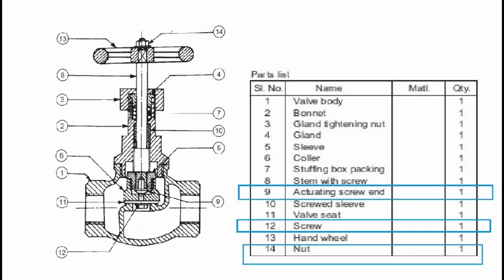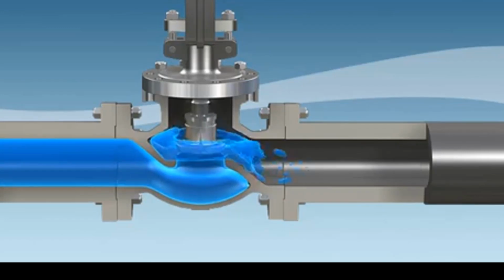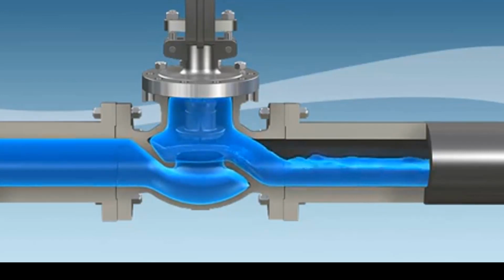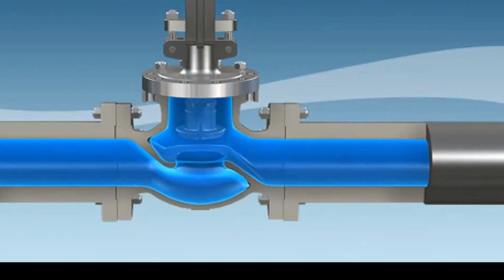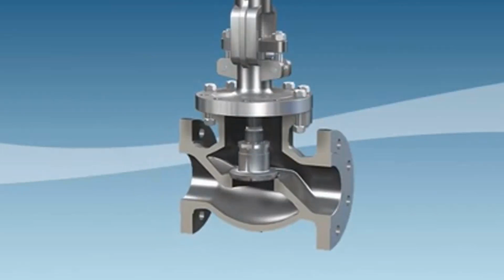This week we are going to make a valve assembly. We use valves to control the fluids. In our example, we use metal-to-metal contact in order to prevent the fluid flow. And we use this metal-to-metal contact between the body part and the number 6 of the collar.